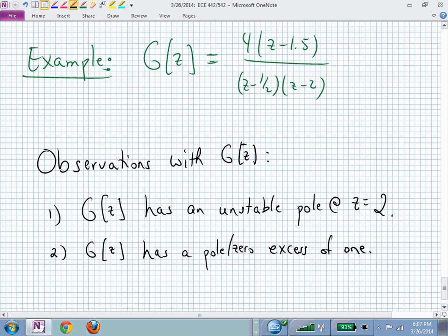So anytime you have an unstable zero, you go, oh no, this is going to make it a little bit more difficult. You can't just really hit your system hard. By that I mean you can't really crank up the gain necessarily with an unstable zero. Things could go haywire. So that puts a little bit of a twist on your options.